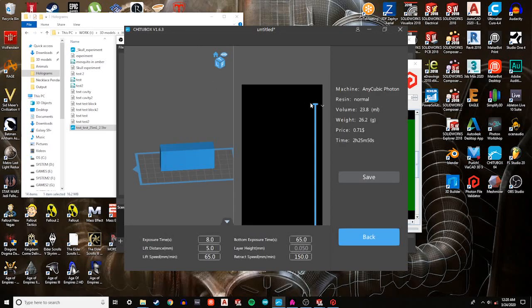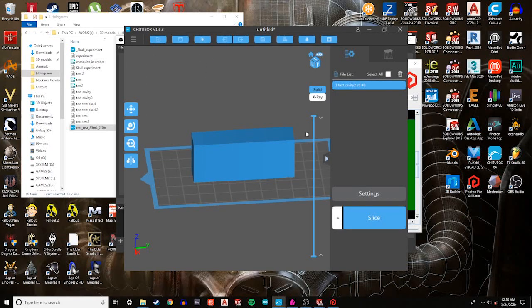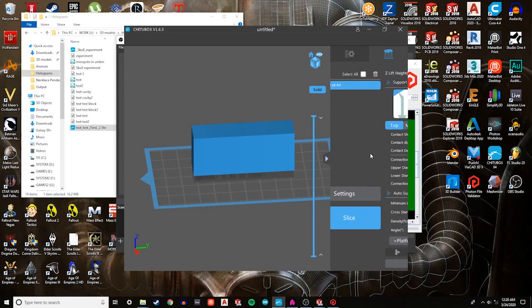So you can come right back to Chitubox, and actually what you can do is once you click on this and drag it a little bit, you can page through it with the arrow keys individually and get exactly to the layer that you want to, and then you are able to fix that island and add a support manually right here.